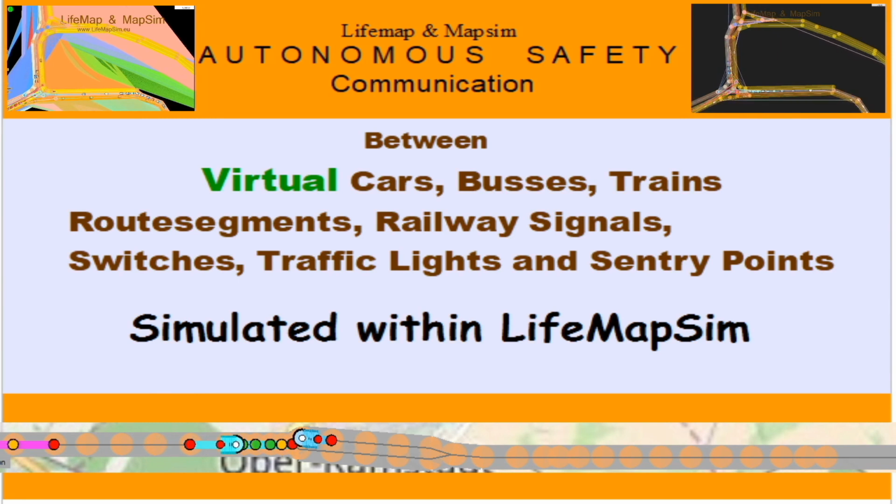Driverless trains are pushing their safety range forward by booking segment after segment at a forward distance corresponding to their speed. The stationary train cannot go ahead as long as the single track to enter is booked by an upcoming train in the opposite direction. Because of being in standstill, or respectively because of not being able to book forward, no ahead safety range is seen.